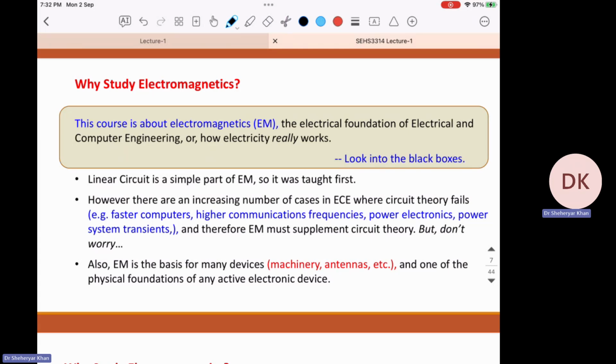In order to properly model those circuits and solve for these parameters, we need to understand, apart from V, I, R and the power, some external parameters. So what are those external parameters? For example, for a capacitor, you must know what the material is, right? Whether it's air, mica, glass, or water. This will determine the value of the capacitance. When you know the capacitance, then you can find out the energy stored in the capacitor, right? So V and I are not enough.